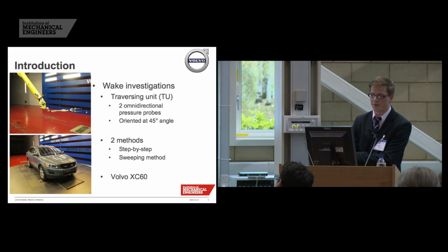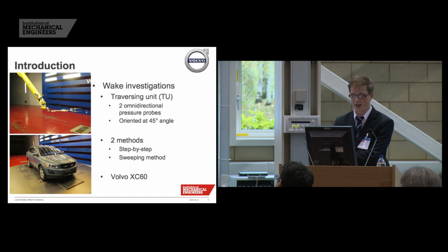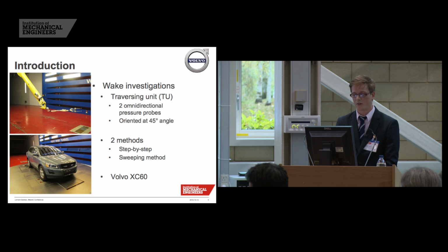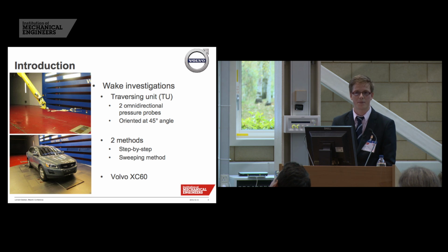When we make wake investigations behind the car, we use a traversing unit where we attach two omnidirectional pressure probes, oriented at a 45-degree angle. And then we have two methods to take these wake measurements.